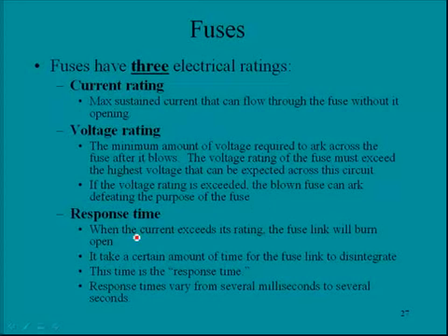Response time. When the current exceeds its rating, the fuse link will burn open. It takes a certain amount of time for the fuse link to disintegrate. This time is referred to as the response time. Response times vary from several milliseconds to several seconds, and due to the type of circuit, the response time will have to meet those needs. If you have really sensitive circuits, you may need a fast response time. Not so sensitive circuits would not need a quick response time.